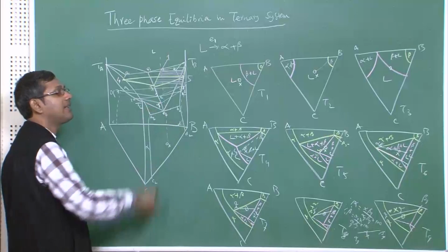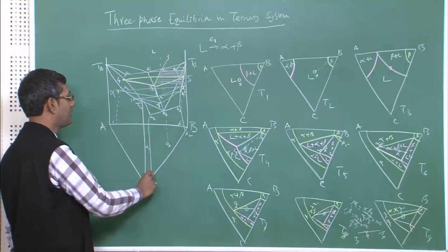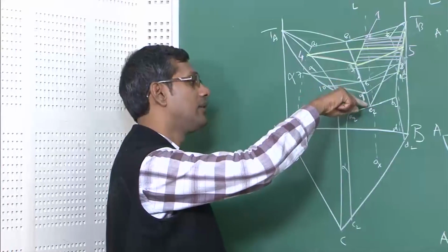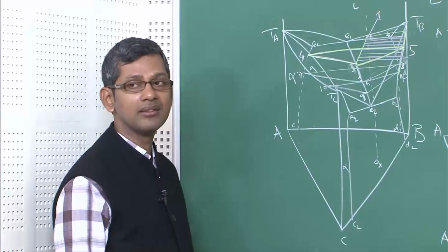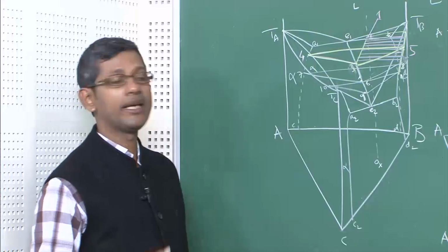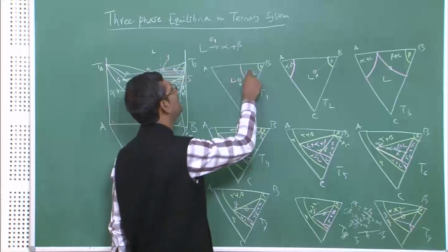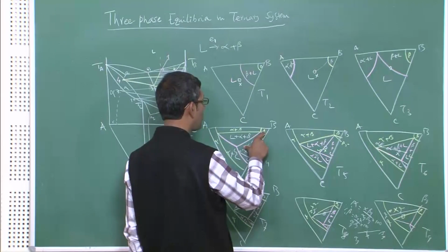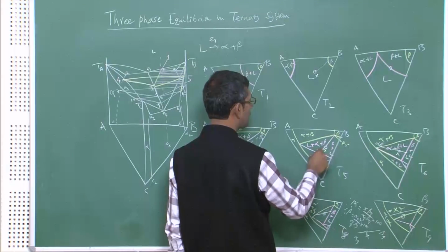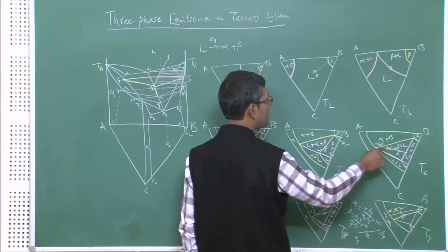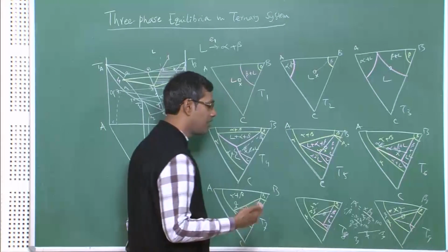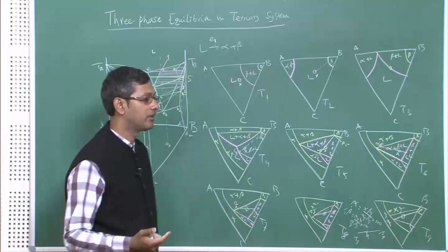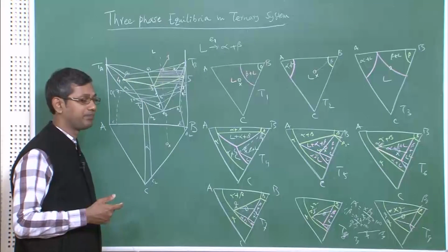Finally this will end at a temperature at which, in this 3-dimensional structure which I have drawn, the alpha plus beta phase field surface will have point 9 sitting on it. That is why the whole solidification will finish. So, the same thing is seen here: liquid initially, then liquid in contact with beta, more and more beta crystal will form, then it will move into the alpha plus beta plus liquid zone, where alpha will precipitate, more alpha means more eutectic, and finally it will move into alpha plus beta where the solidification will get over. That is how things will happen, and this is what you need to follow, correct.